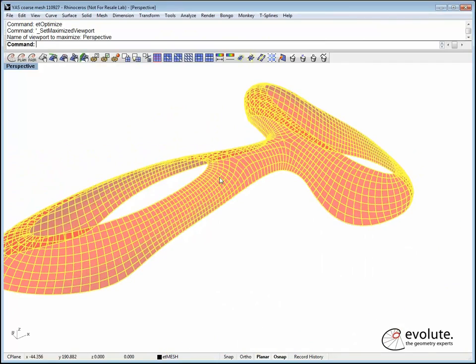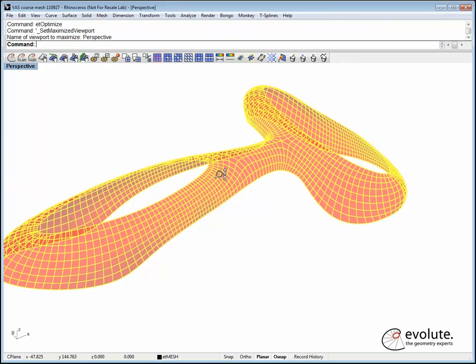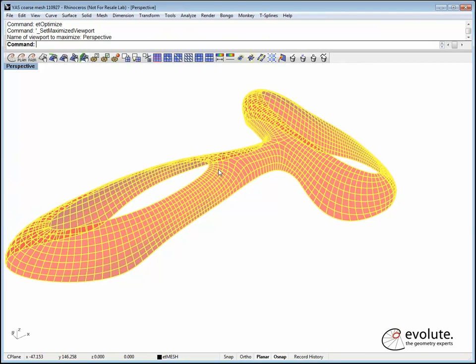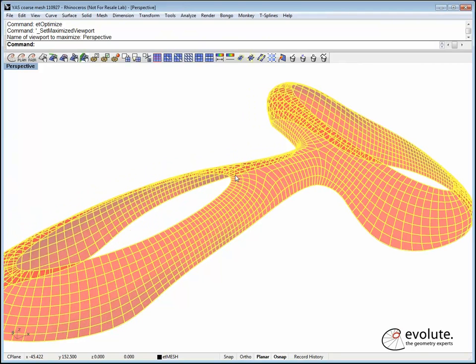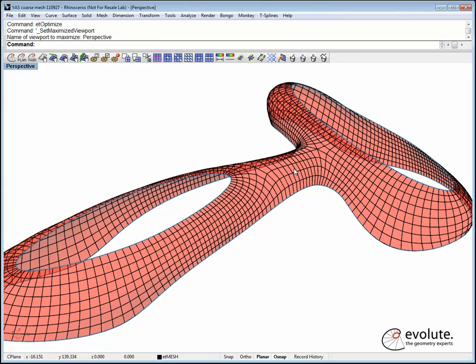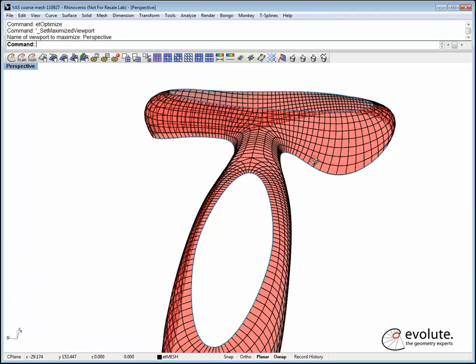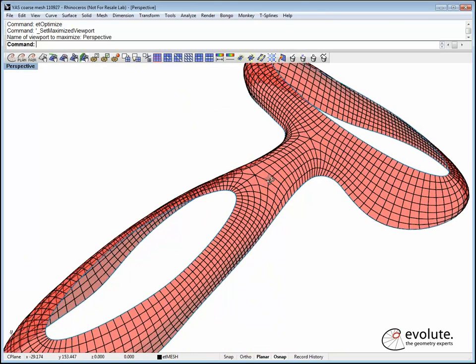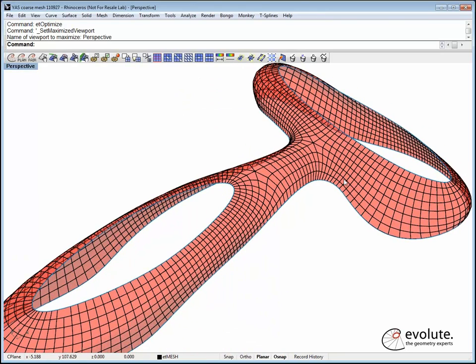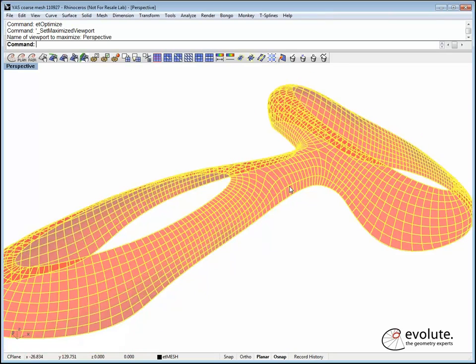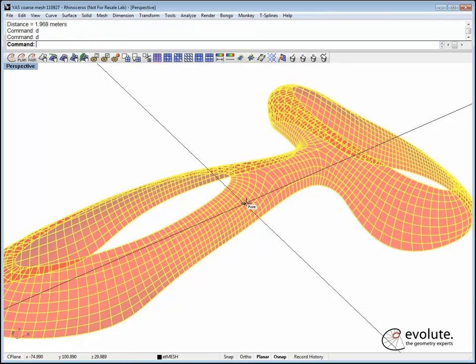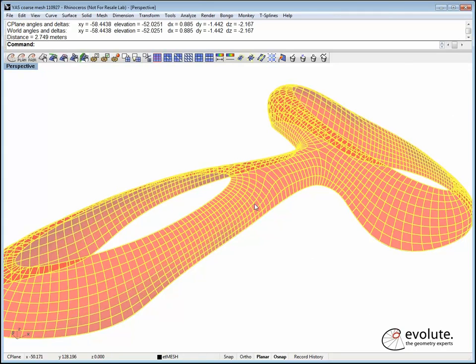So in order to get that diagrid impression again, we'll have to subdivide this slightly optimized mesh. This is now basically optimized for fairness and a bit of coplanarity, just to keep the major distribution of panels in shape, you know, to align, for example, with this spine here. So let's do a Catmull-Clark again, or actually this size is quite good.